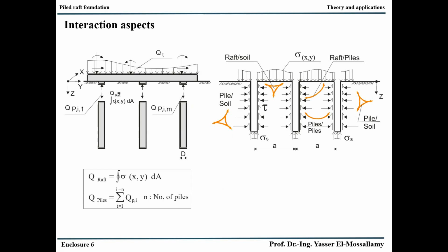It is a very complex soil-structure interaction between the structure, the raft, the piles, between the piles and the raft, and this mutual interaction makes this system very complicated, and then we need really very complex finite element analysis, mainly three-dimensional finite element analysis, and till the end of the last century, it was very difficult to carry out such analysis.